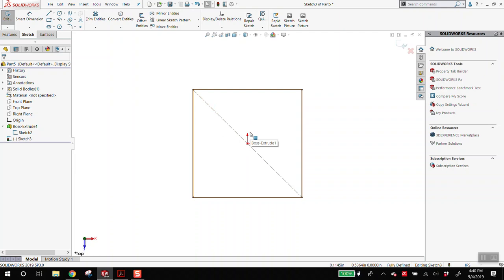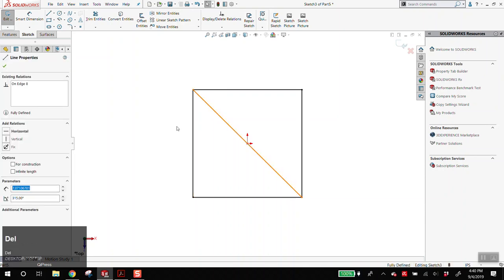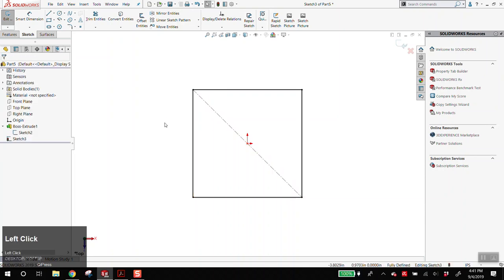The construction line. Again, that's another property of construction lines. When you convert entities, if you select the whole sketch, it's going to ignore construction lines. If you want to copy a construction line, you actually have to select it and then hit convert entities if you need it or want it. So convert entities is copy. A short answer, yes, convert entities is copy.